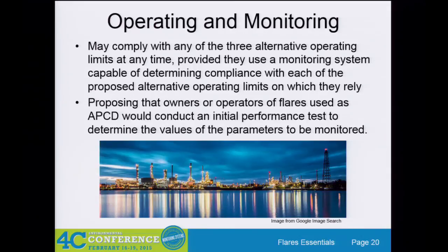So they gave you those three options: the net heating value, the LFL, or the combustibles content. And they were nice enough to say you can pick which one you comply with. We're not going to force you down one path. You can pick, or you can comply with all three. It's kind of up to you, but it will push you towards what monitoring you're going to put in place.